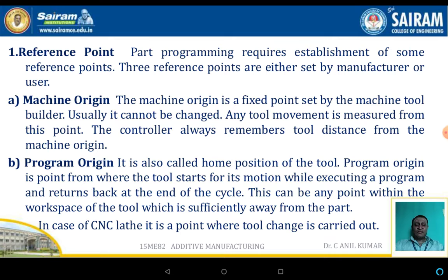This can be defined by the programmer, and this can be any point within the workspace of the machine tool which is sufficiently far away from the part. In the case of the CNC lathe, it is a point where the tool change is carried out.